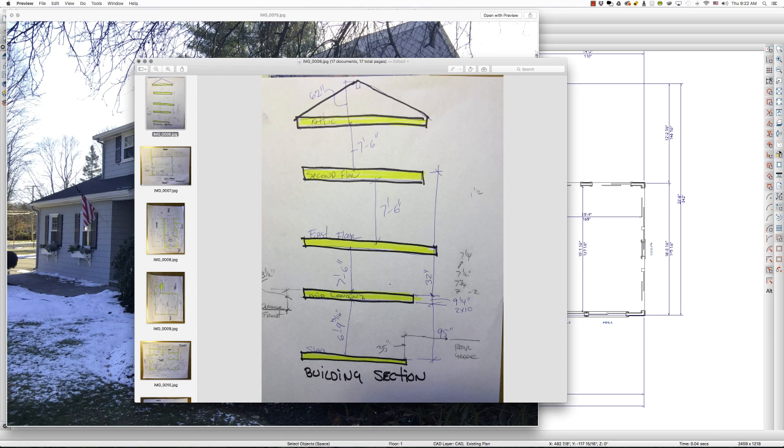Right now I'm going to work on the level between the mid-landing and the first floor. You could choose different ways of doing it. I have chosen to do the mid-landing as my 0 point in elevation because that's where the front door is. You could choose first floor as 0 point and go -32 down to the mid-landing, but I've chosen mid-landing at 0 point and up +32 to first floor.